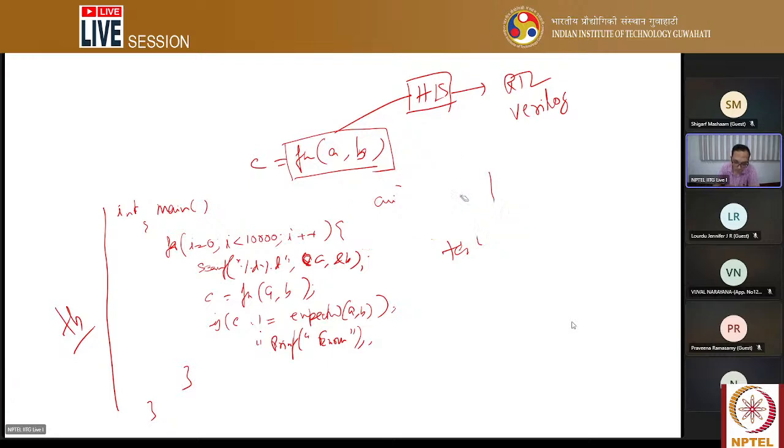Now, I hope all of you have already installed Vivado HLS and tried to synthesize some C code. When you try to include the file, you have to say which is the top level function you want to synthesize. You have to mention that this is my top level function, okay, this fn. And this fn in turn might call many other functions like fn1, fn2, any other functions. But you have to mention the top level function you want to synthesize. Also you have to mention your test bench or test file. So you have to say this is my test file. This may be tb.c, and this function is written in some other file, say src.c. So you have to give these files to synthesis, and mention this fn as my top level function, and this is your test bench.